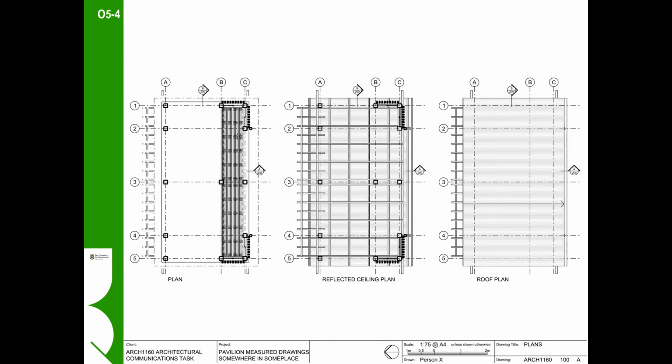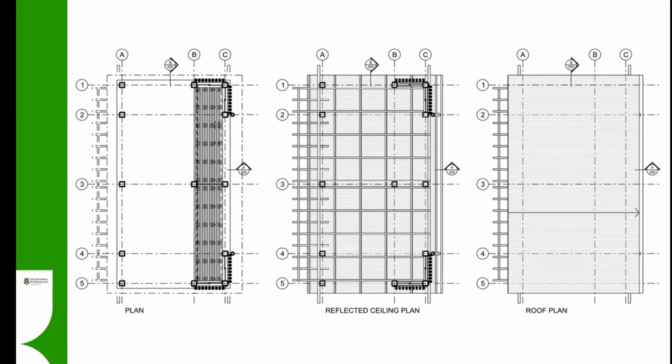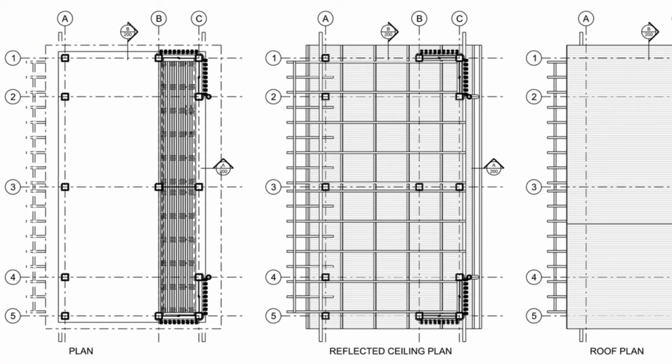Once all the drawings are complete, it is time to arrange and coordinate the separate drawings on the final layout sheets. In this instance, we are laying out the plans on one sheet and the elevations and sections on another. We are including a simple title bar running along the bottom of the sheet. Typically a title bar would run along the right hand side of the sheet as a column, but in this instance it's okay to provide a more subtle title block along the bottom, as we are not producing a construction set of drawings. Make sure that we retain the grid referencing and that each drawing has a title.